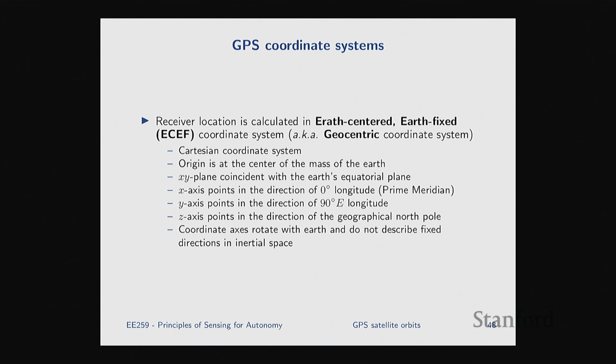It involves having a model of what this orbital trajectory looks like, which is always modeled by an elliptical trajectory. But this needs to be done very, very accurately, so it's actually a pretty challenging problem. You have this satellite 20,000 kilometers above you, going at very high speeds. You're on Earth, which is rotating. There are a variety of forces that affect the satellite, from Earth's gravitational force, to solar radiation, to the emission of different gases from the satellite that can change its trajectory. So there are all sorts of different effects that make this trajectory not a perfect ellipse.